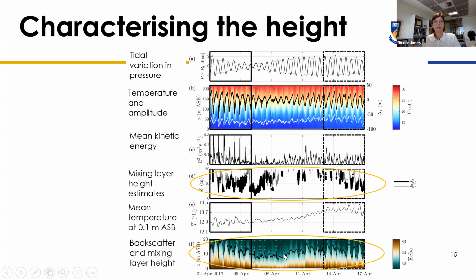So here we're basically assuming that the sediment can always be mixed up to the height of that lower pycnocline, that near bed pycnocline, that's essentially trapping the transfer of momentum and material above that height. And so we're assuming there's always enough momentum to resuspend the sediment into the highest portion of that well mixed region.